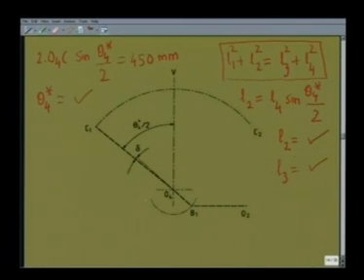again obtained the path of B, which is this circle. And O2B1, as we know, was L3 minus L2. So from O2 I draw a circular arc O2B1 as L3 minus L2. So I get the extreme position O4B1, and the extreme position O4C1 is already known. So the angle between the extension of O4B1 and O4C1 determines the required value of delta, which as